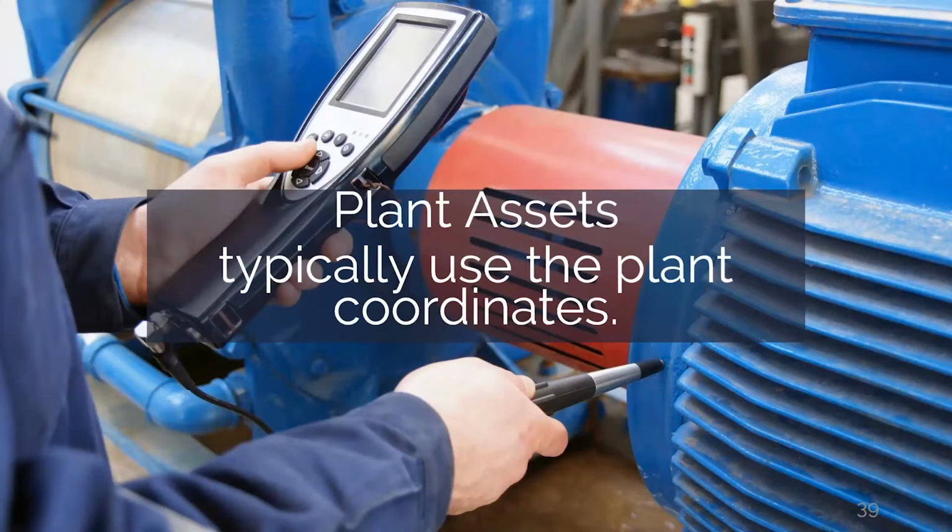So inside of a water treatment plant, if I'm doing an asset inventory data collection process, I'll often just hang the GPS on the door and use the same coordinates for everything inside, because once I've found the building, I've essentially found everything inside it. Of course, there's a scale issue there. If it's a really large treatment facility, I would probably want to narrow that down, maybe do things building by building or floor by floor.